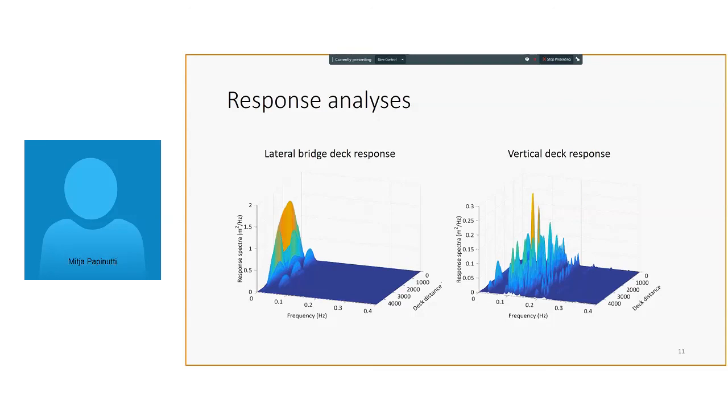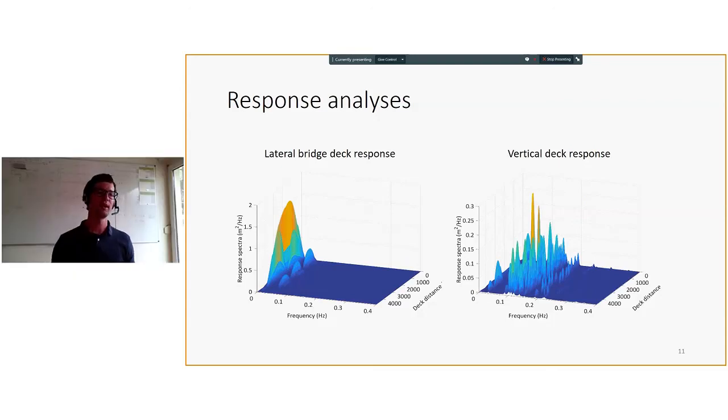So you're saying that the lateral mode and the vertical modes are somehow combined due to the large lateral motion? Yes, I definitely agree with that, and I think this is one of the main reasons why we were in the first place trying to do nonlinear time domain simulations, so that those coupling effects and nonlinear effects could be observed there.